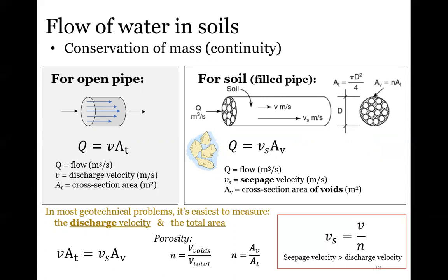If you remember when we were doing the original phase diagrams, we talked about void ratio and porosity and how they're very related. There's that one equation that converts between the two. I said to forget about porosity for now because we use it heavily in permeability. This is it now.